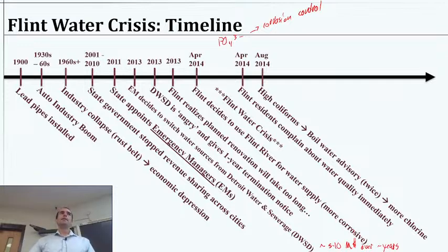That means they did not have enough treatment capacity to chlorinate in the way that they were supposed to and have enough contact time, right? So they probably didn't have a big enough reactor, essentially, to do the treatment that they were actually required to do. So what did they do? They ramped up the chlorine, right? So they added more chlorine.